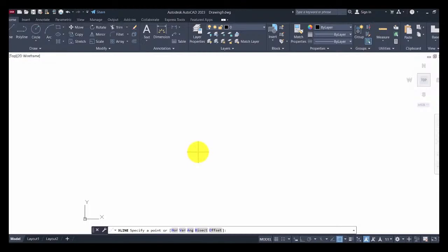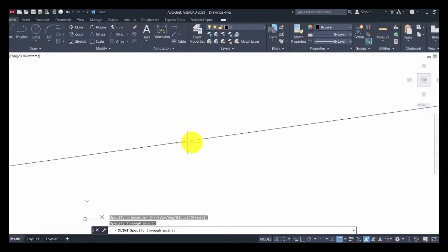There is a unique way of using construction line. One unique thing about construction line is that it does not have a beginning, it does not have an end. On my screen, you can see a construction line is a very long line, no beginning, no end. It's similar to what you use your T-square for. If you are doing technical drawing, your T-square is very long and it spans across your drawing sheet. What you do with your T-square, drawing a very long line, is the same thing that your construction line does in AutoCAD. So the construction line is a very long line, no beginning, no end.